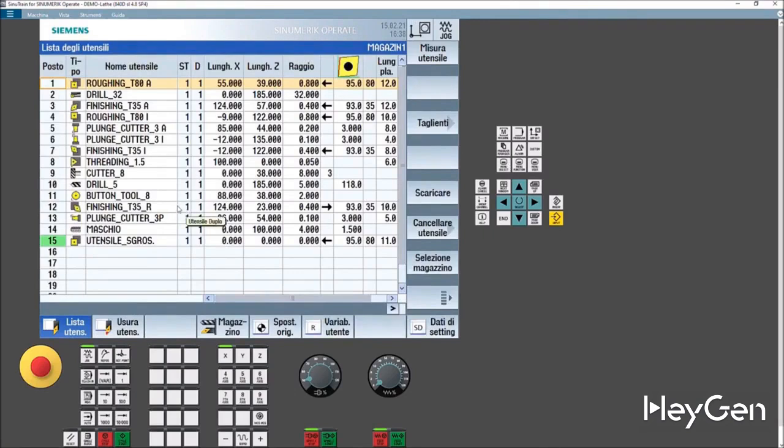To load new tools, there's a series to insert, including special tools. There's a collar for dual turret machines. Star probes, drill bits, and mills, even with angular heads, are available. Favorites are pre-seen tools. In ShopTurn, insert missing tools. Prepare the tool table beforehand or add tools while programming. If a drill bit is selected in position 2, it needs to be placed.